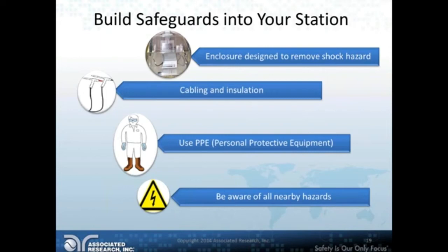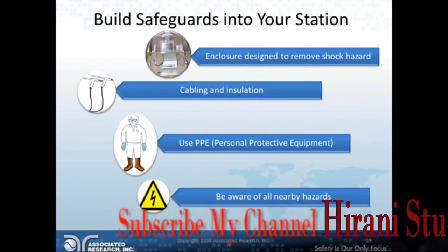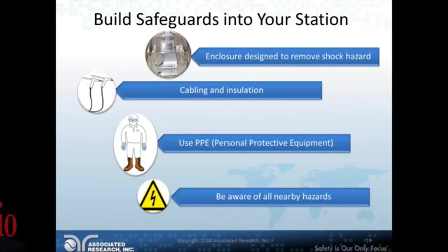You see a picture there of a guy with safety glasses. That's if something sparks, you don't want little pieces of metal flying around in your eye. High voltage gloves, which I use very regularly, and I have gloves that go up to 10,000 and 20,000 volts depending on what I'm working with. That picture also shows lineman boots. Not for everybody. You probably don't need lineman boots in all environments. It's never a bad idea though, because it's going to insulate you from ground potential. And then just being aware of all nearby hazards. As per OSHA regulations, qualified operators have to be qualified to work in their particular environment, and they have to have that training in order to do that.